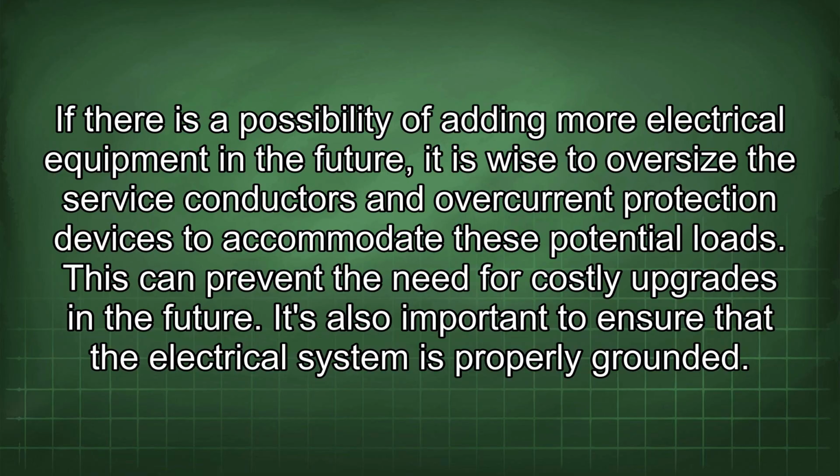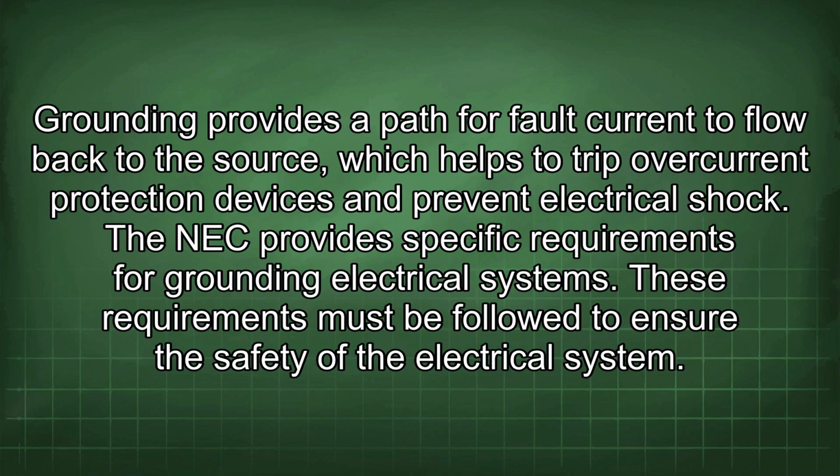It's also important to ensure that the electrical system is properly grounded. Grounding provides a path for fault current to flow back to the source, which helps to trip overcurrent protection devices and prevent electrical shock. The NEC provides specific requirements for grounding electrical systems. These requirements must be followed to ensure the safety of the electrical system.